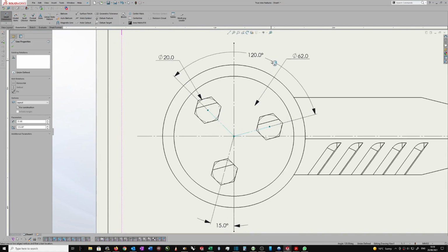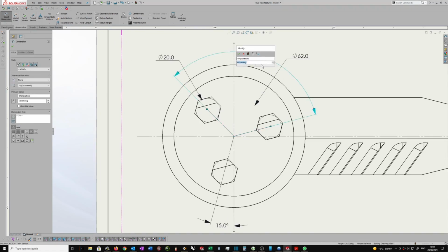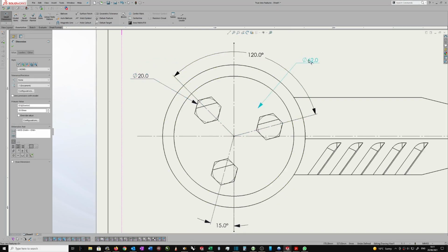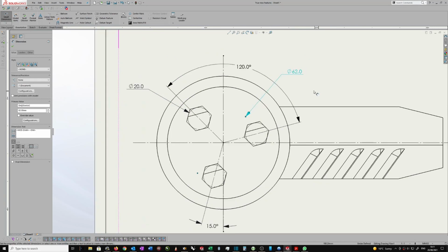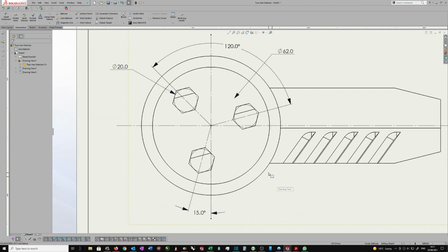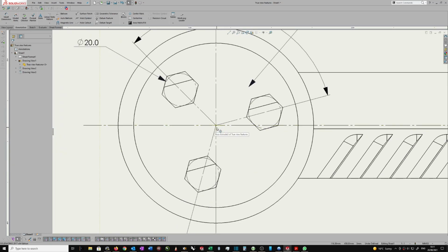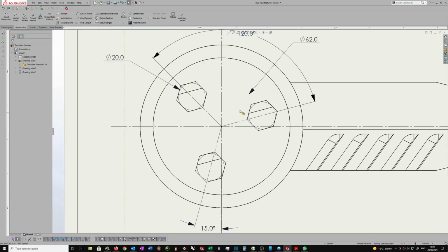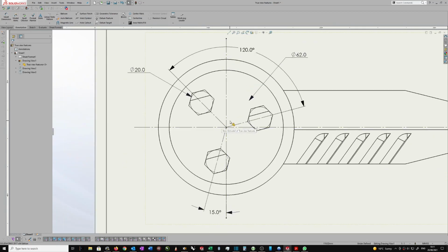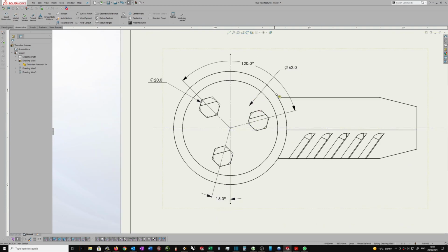So it is quite simple, and there's no difference between SolidWorks 2017 and 2020. They work exactly the same in all these respects. So when I said yesterday it had to do with changes or updates in abilities in 2020, that's not true. Right, so from here, oh yes, okay, so we really should get rid of this. So just keep that in mind. If you are going to put center lines in, take the center mark out because it just causes problems.